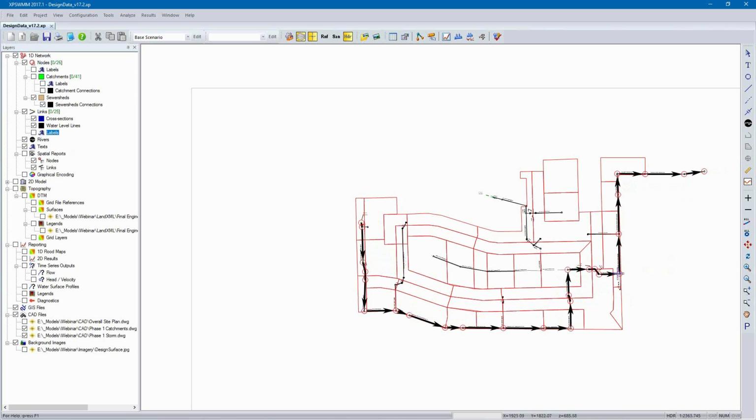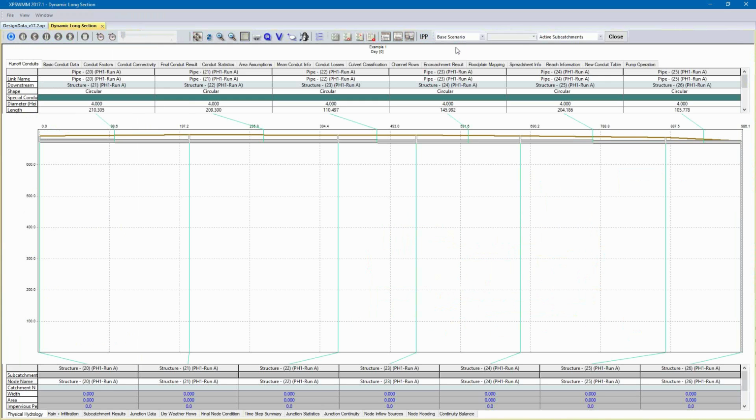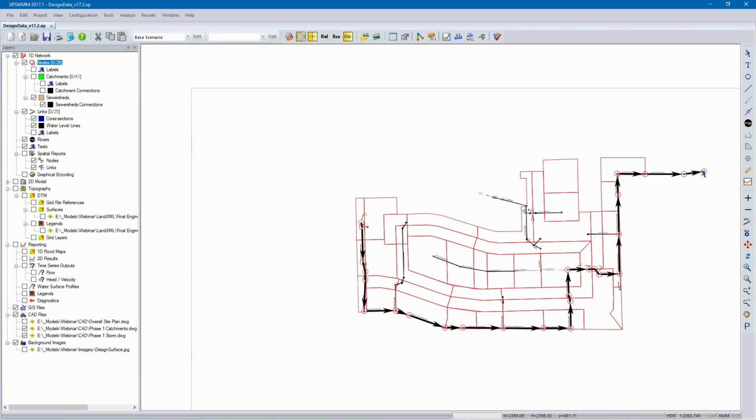And we can investigate what we have. Select all those. I want to take a look at this end profile. And we can realize that, wait a minute, as with really any of this data information, we need to use a keen eye, if you will, to notice the fact that even though I'm getting pipes with the correct diameter, and it looks like I've got rims and I've got some inverts, occasionally there are some things that these formats don't handle well. In this case, our outfall has a 0 value in it.